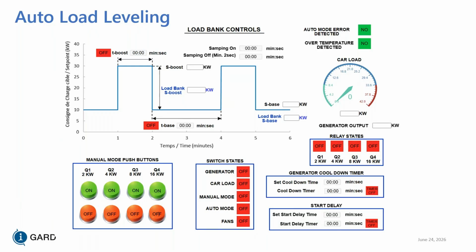Is there a load bank that provides AC and DC? It's more difficult to have. I think you're asking if you can combine AC and DC, and the issue there becomes how do you cool it unless you have an external cooling system. There are not very many cooling motors or blowers that have both AC and DC operation unless you have an external supply.